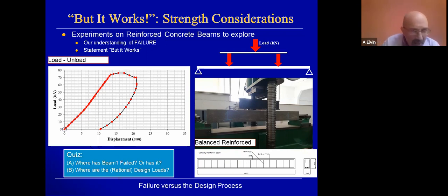Sorry, before we do that, let me show you the unload curve. So we've loaded and now we've unloaded. Can you see we've unloaded? Can anybody tell me if this beam has failed? Who says yes? This is a little bit more information, unloading information. Helps you? Yes. Plastic failure? Yes. Consensus? Yes. Not return to initial form. Excellent. All right. Let's see what's on my next.